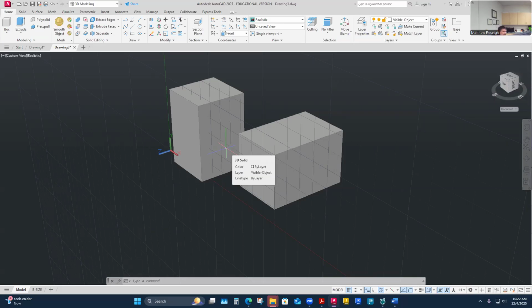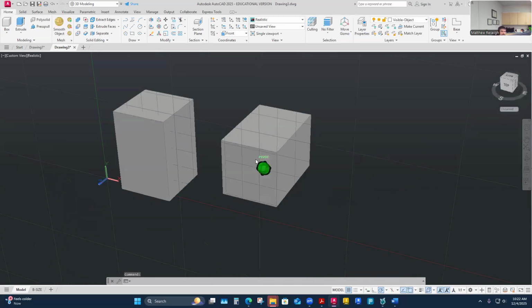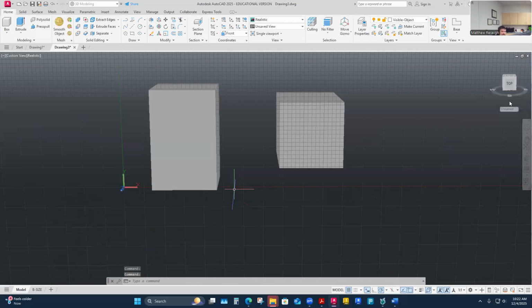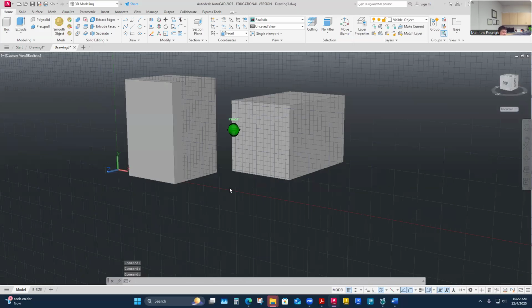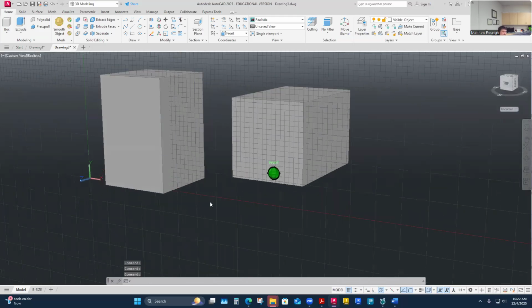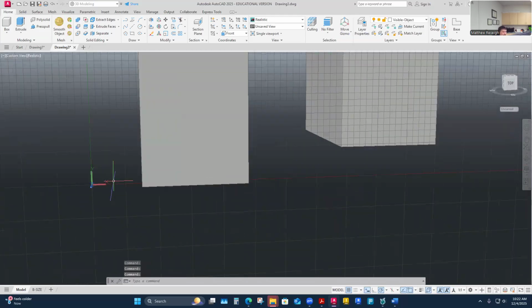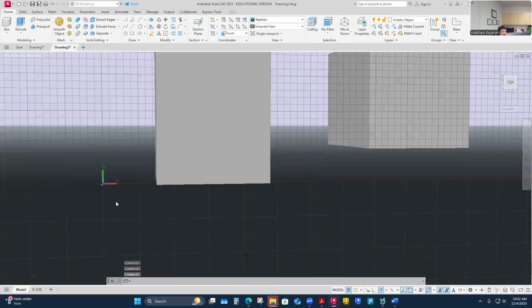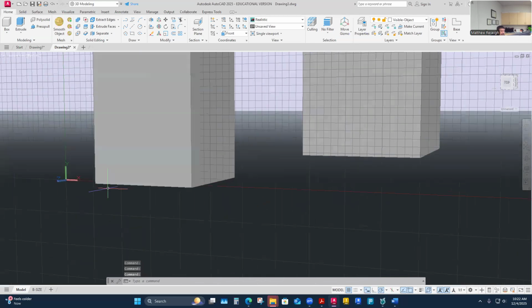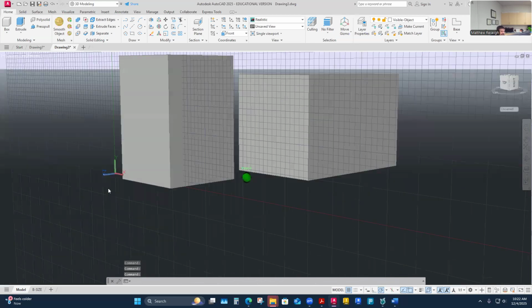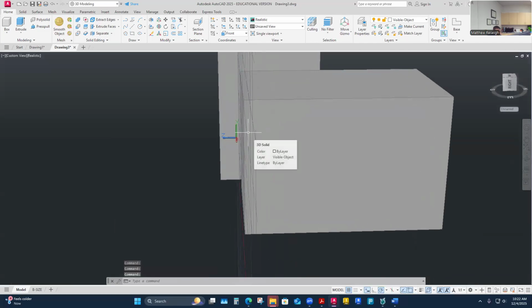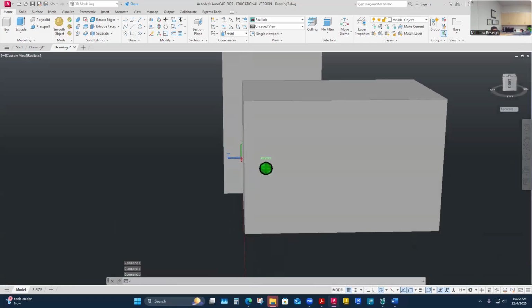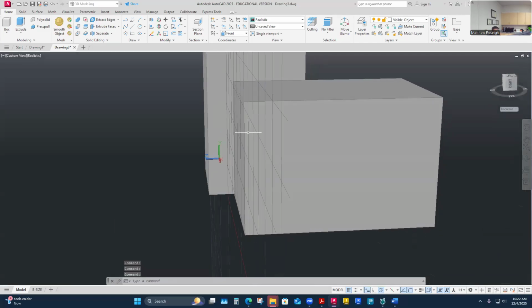Like I went to the front grid, which is even more confusing because your thing actually says it's like the top over here, but this is what the grid system considers as the front. It's like X and Y in our orientation for 2D drawing, and Z was either coming at us or away from us. So when I went to the front grid and clicked 4x4, it started with the base on the Z at 0 essentially. So it's on this Z plane of 0, and then I dragged it that other way 6 inches.